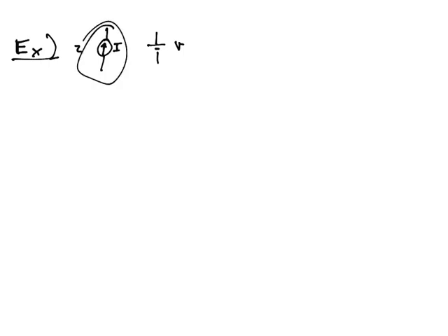So this is just an element that can be placed into a circuit, just like a voltage source is an element or a resistor is an element. Well, now we have a current source. This may be some big, huge electronic circuit. We're going to focus on a little bitty part of that circuit. And so we may show a current source, but that current source may really be a symbol for a bigger part of the circuit that we're not going to worry about. All we know is that because of this thing, we know how much current flows right here. And that's what the current source tells us.